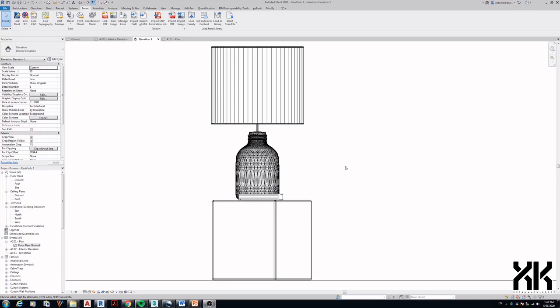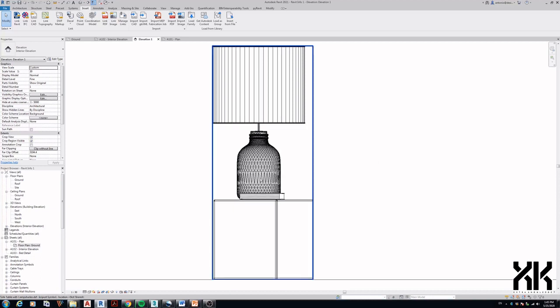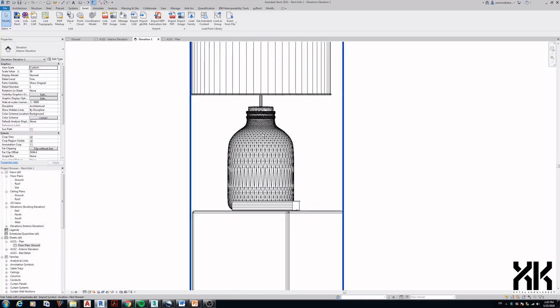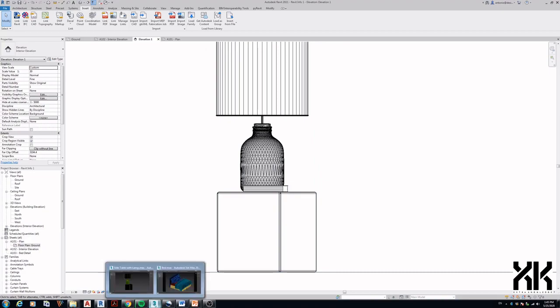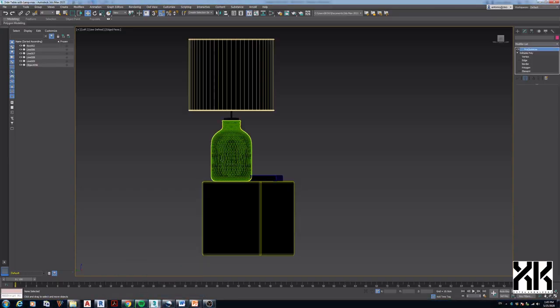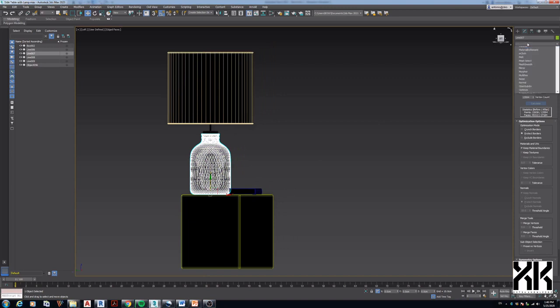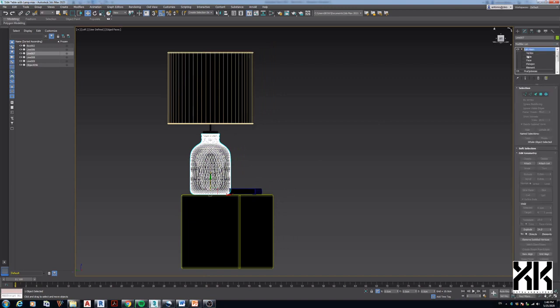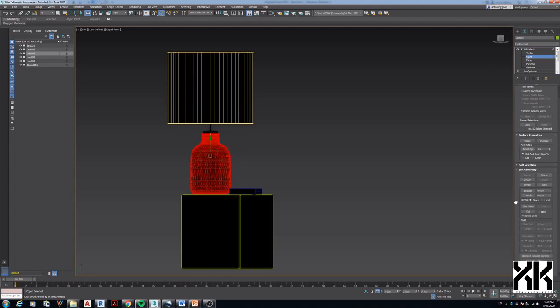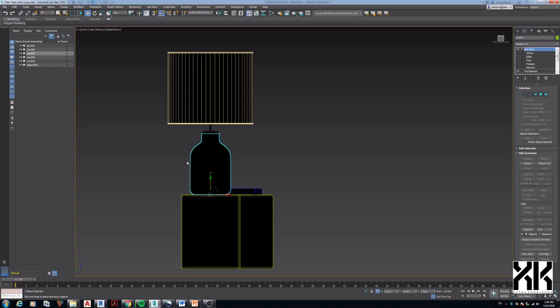Once imported, you will notice the result is still not for drafting because the base is full of mesh, but could be used for other presentations. To remove the mesh, we will add the Edit Mesh modifier. When loaded, select Edge sub-object under the Edit Mesh modifier and select the object. Under Surface Properties, click the Invisible button and see the changes in the object. Let's export the models once again and see the result.